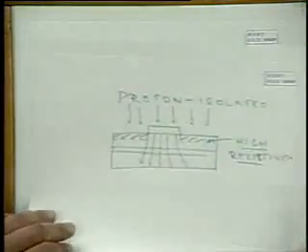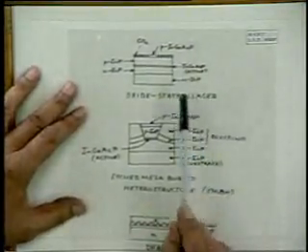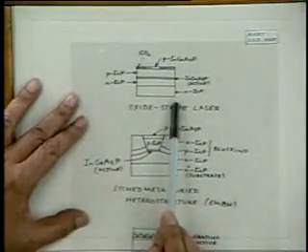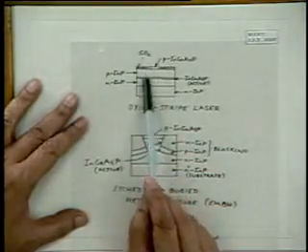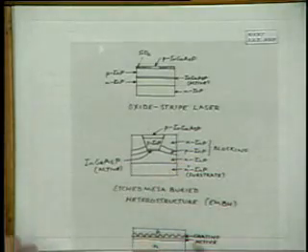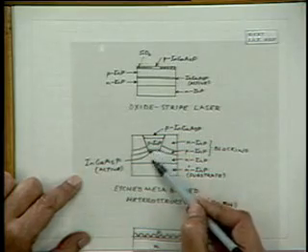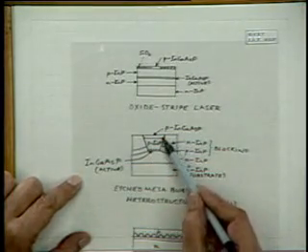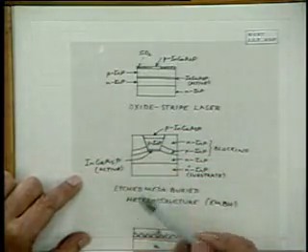These were in the first years of laser fabrication, but more recently, you can use junction isolation. I'm not sure whether you can see this. This is an oxide stripe laser. You have an oxide. Here, this is a p-n junction isolation. Here you have a p plus. This is the active region. And here you have the p-n junction, which is reverse biased. So this is by multiple growth.